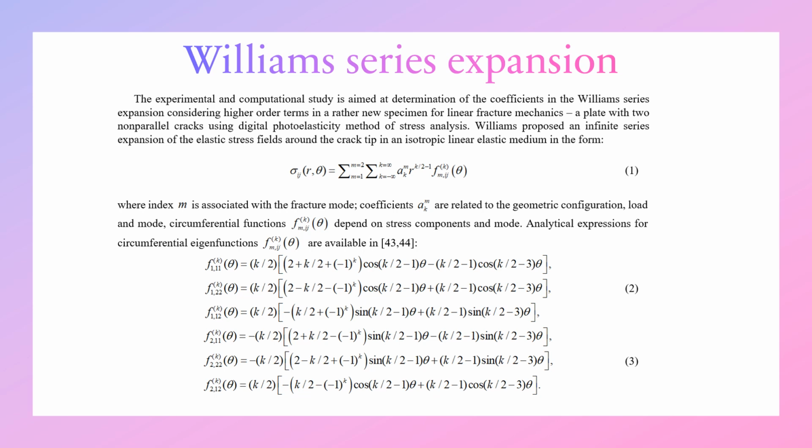Williams series expansion is well known in linear elastic fracture mechanics and has the form where A and K are coefficients related to the geometric configuration, load and mode of loading.